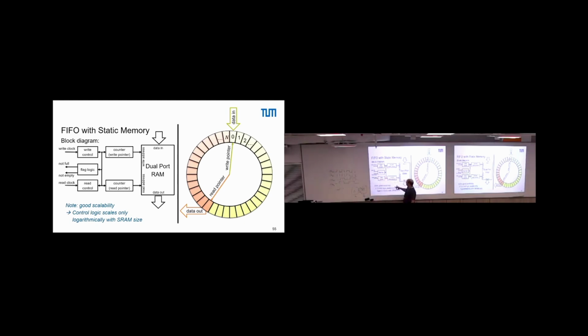Now back to what is synchronous and asynchronous. We have this write clock. We write data, and with the write we trigger the not empty signal, because as system B you need to know there is something available. But this is exactly the point where you cannot rely on the clock that comes from here and the clock that comes from there, which effectively triggers the logic.